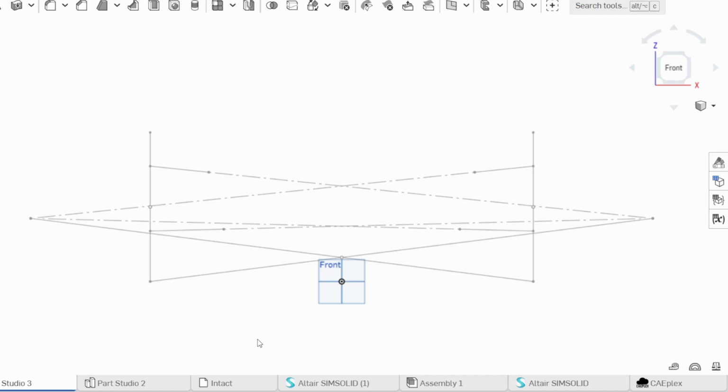To quickly go over what roll centers are, we'll look at the sketch here. We have the wheel center line, left and right, and then upper A-arms and lower A-arms, and lines projected from the A-arms. And where they meet is the instant center. So the instant center is going to have a vertical and a lateral dimension to it. Then if we take lines from the bottom of the wheel contact center and draw a line from the wheel center to the instant center, we'll get these two lines, and where they cross is the roll center.